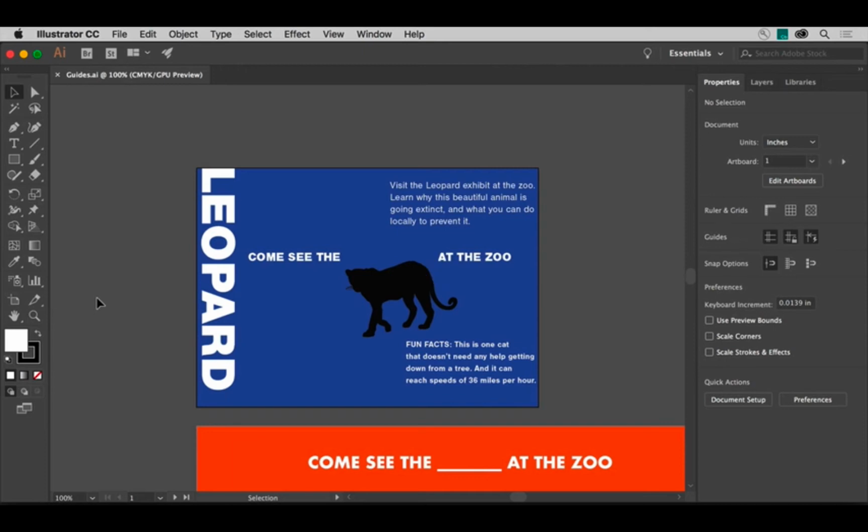In this tutorial, you'll learn how to align content in Illustrator using ruler guides you create. Now, ruler guides are useful when you need to have what I like to refer to as a persistent alignment. So if any content you bring near the edge of an artboard needs to be a certain distance from it, like maybe a ½ inch, you can draw a guide and leave it there. That way you can snap content to it.